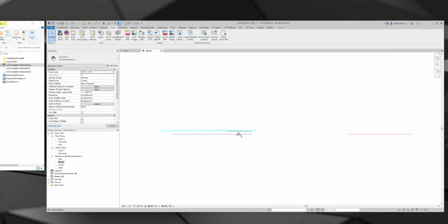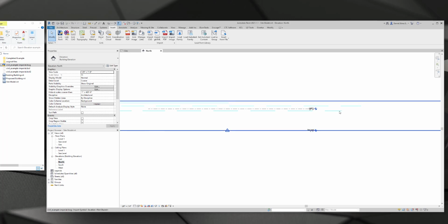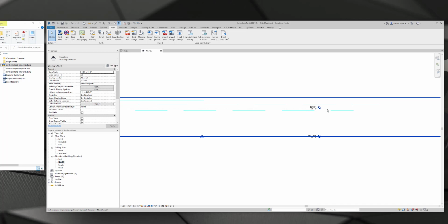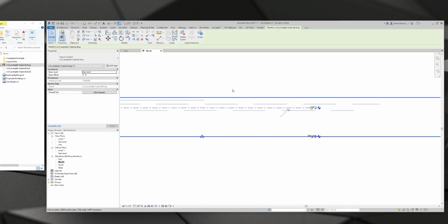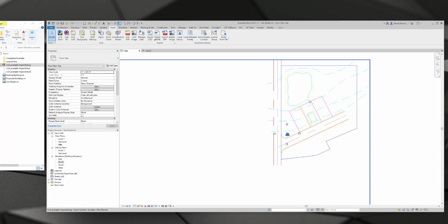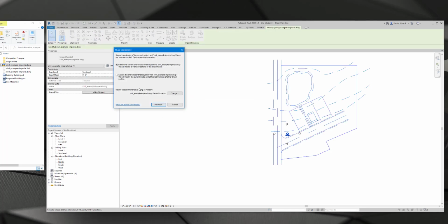Notice there's the survey point. It aligns with sea level. And if I pick the CAD file, just hovering over it, actually, you can see the bottom bounding box aligns with sea level. And you remember that one contour is at 20 feet. So from here up is 20 feet. So this is all good. So the next step then is to acquire shared coordinates.